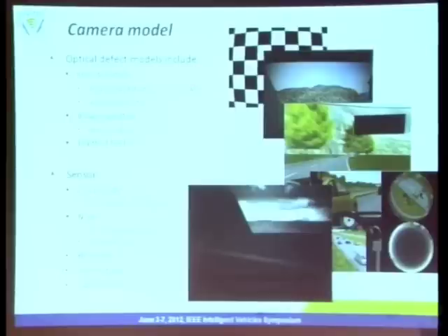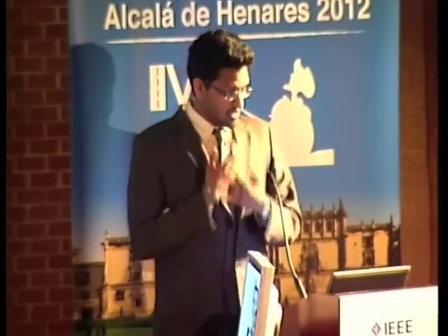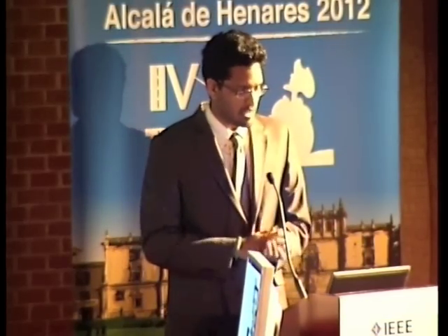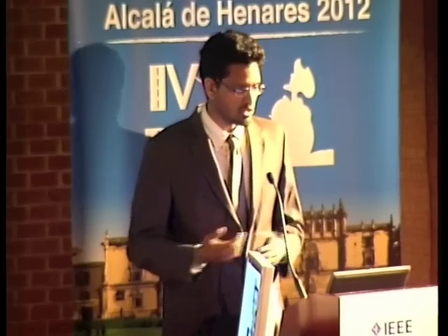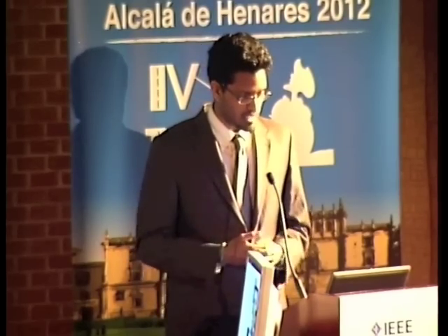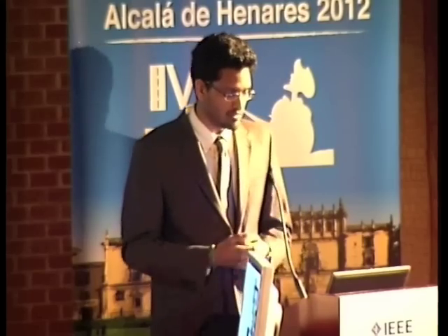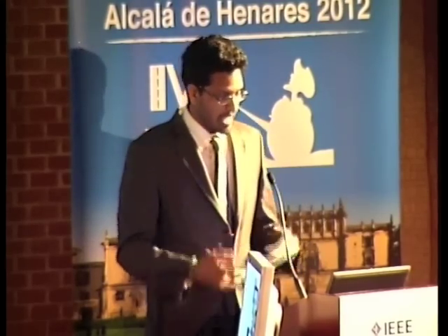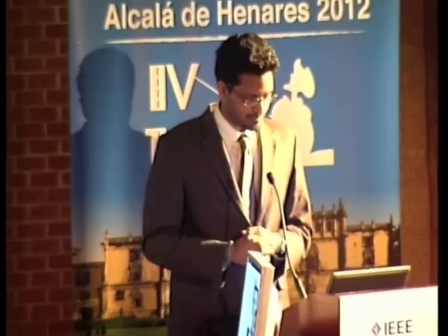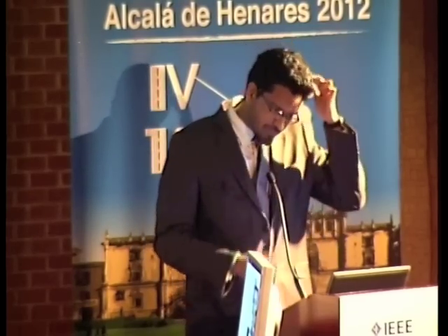And for the sensor itself, taking into account the color filter array or a generic color transform function, different sources of noise, that means it can be the read noise, the photonic noise, sensitivity, non-uniformity, and so on. Blooming for the sensor, the kind of shutter, if it's a CMOS that is subject, for example, to a rolling shutter, and things like gain control.